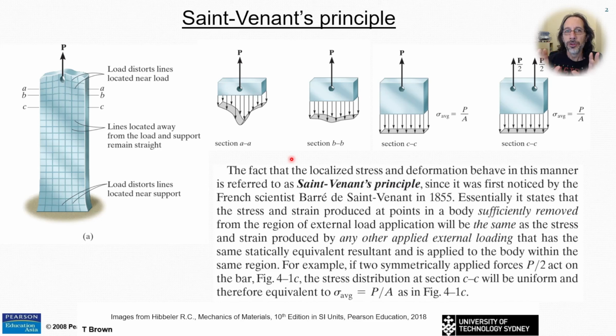But when you go to do stress simulation using finite element analysis, this becomes really important. It really helps you to simplify your modeling and to interpret the stress and strain that you're seeing in your simulation. Without a good understanding of Saint-Venant's principle, you'll often be trying to model too much detail, or you may be looking at stresses that aren't real.